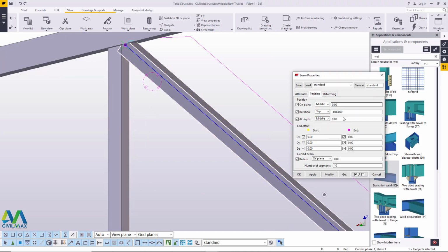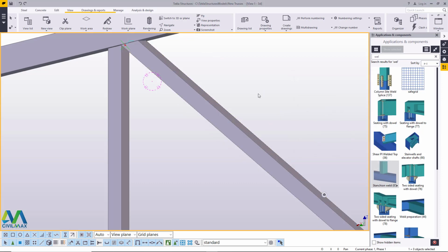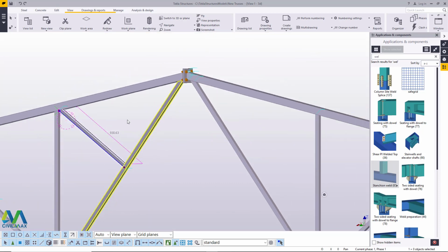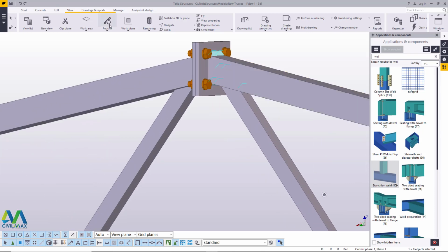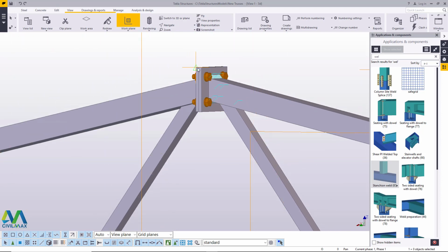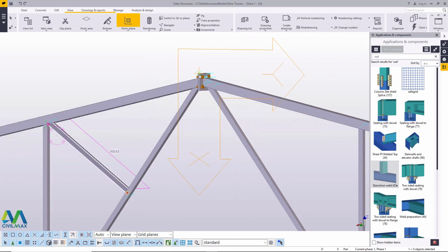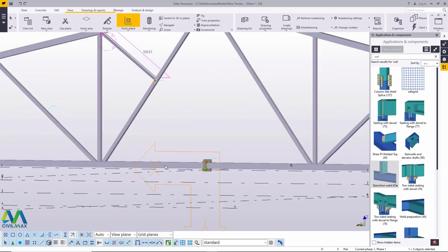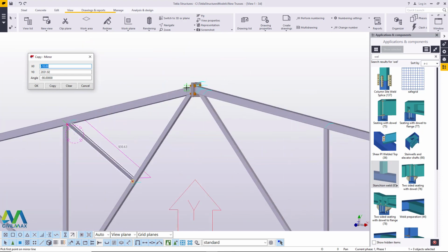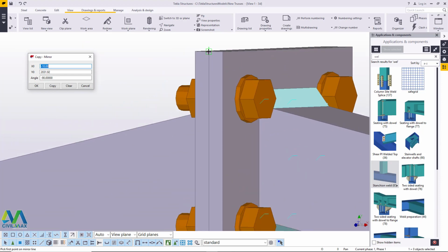Double click on that, and we come to depth and click front. We see that is the position that is best for us. We'll come here and select this, because we want the same member mirrored at the other end. How do we do that? We select that member and change our XYZ plane, and we'll come to the work plane tool here and place our work plane tool in this position right there. Make sure the XY axis is facing the right position. Let me just place it right there. Then right click and come to mirror by picking the right option.